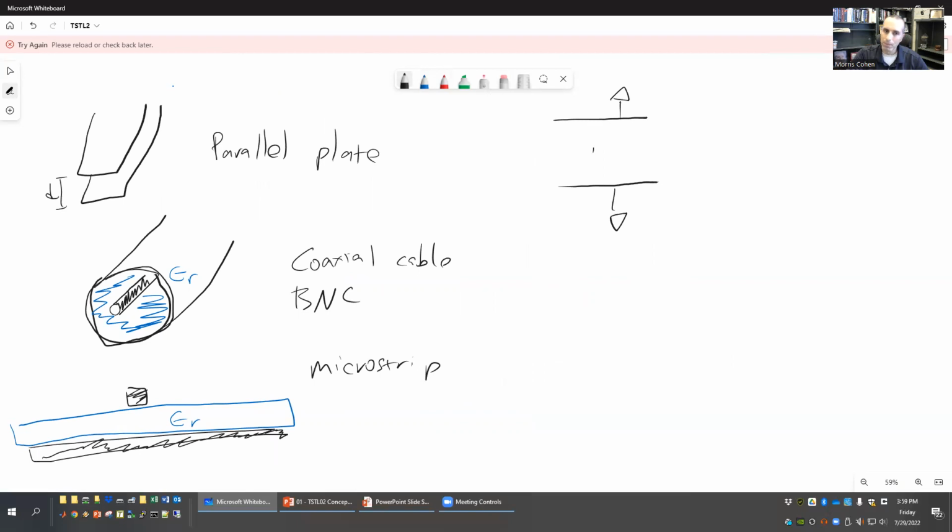And in the middle, I have a wire conductor, right? This is called strip line. This is common in circuit boards where you may have internal layers inside of a circuit board, and you may have two planes, a ground plane on both ends that sandwich that single trace that goes in the middle of the circuit board. And so that's a strip line.